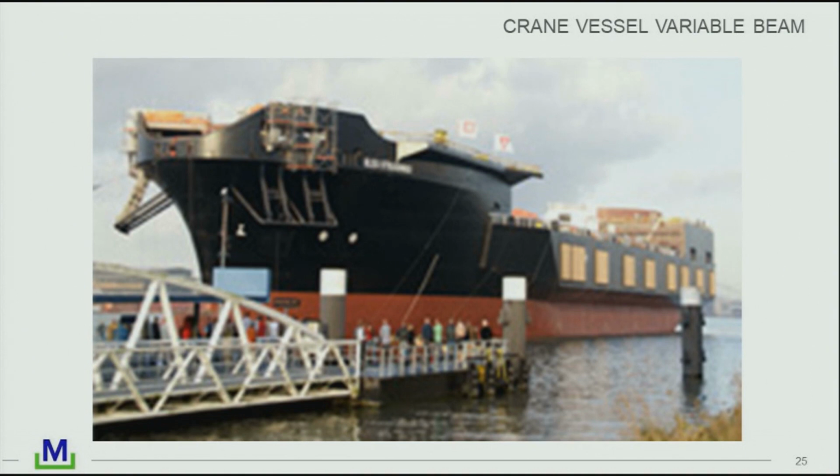Another thing that we do to increase the stability of a vessel is this is a crane vessel. And you can see here at the waterline, it's quite a narrow width that enables it to make a fast transit. But when it's doing the lifting, it ballasts down to this level, and you can see an increased width then, increased stability, which you need for the lifting operations. This vessel's fitted out with a crane now.